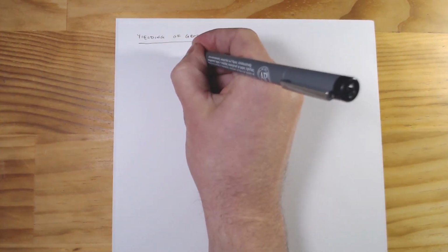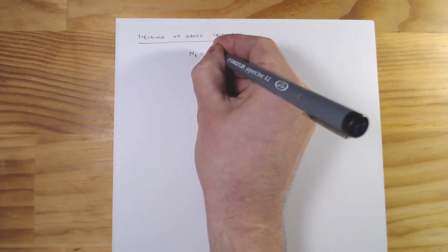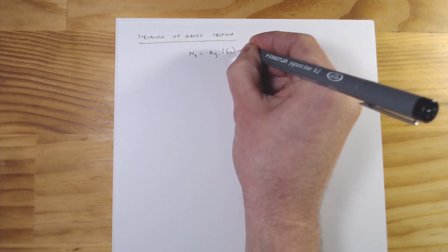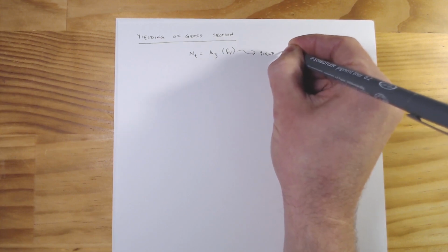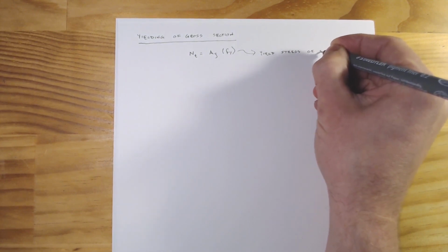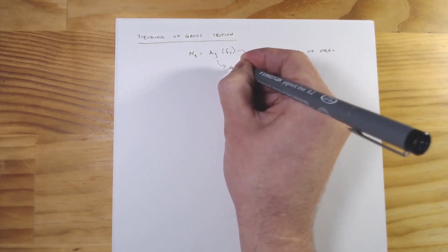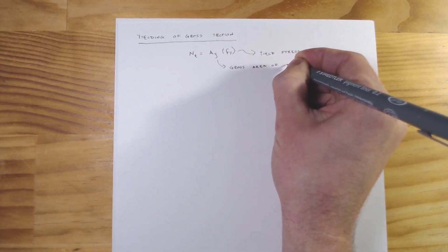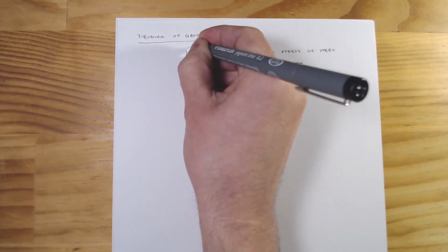The equation for yielding of the gross section, our section capacity N sub t, is going to equal the gross area of the section times Fy, where Fy is the yield stress of the steel, and Ag is the gross area of the section. We'll go ahead and box in that equation.